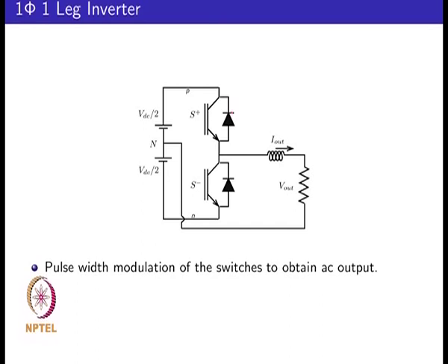So, when you are talking about generating a fundamental output, your fundamental voltage is of the order of time durations, you are talking about 50 hertz or 20 milliseconds. The switching times that you are typically talking about is of the order of tens of kilohertz. So, you are talking about 10 kilohertz, you are talking about 100 microseconds. Okay.